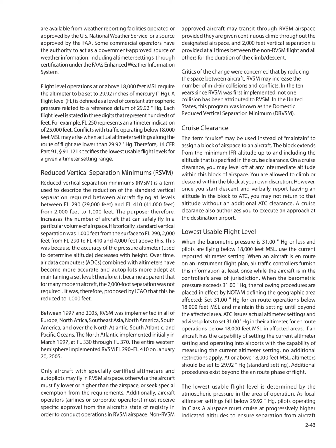Over time, air data computers (ADCs) combined with altimeters have become more accurate and autopilots more adept at maintaining a set level. Therefore, it became apparent that for many modern aircraft, the 2,000-foot separation was not required. It was, therefore, proposed by ICAO that this be reduced to 1,000 feet. Between 1997 and 2005, RVSM was implemented in all of Europe, North Africa, Southeast Asia, North America, South America, and over the North Atlantic, South Atlantic, and Pacific Oceans.